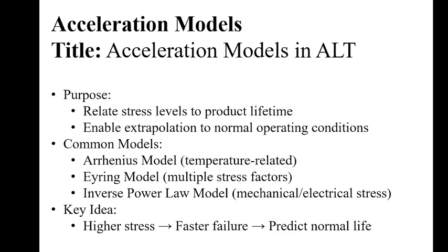Acceleration models are a fundamental part of accelerated life testing, as they provide the mathematical relationship between applied stress and the expected lifetime of a product. These models allow you to take data obtained under high stress conditions and extrapolate it to predict performance under normal operating conditions.